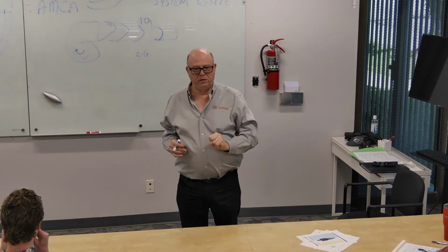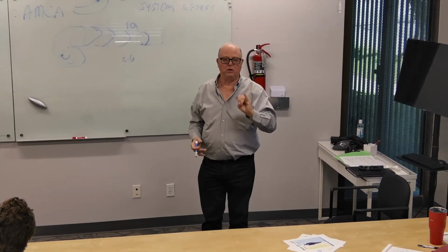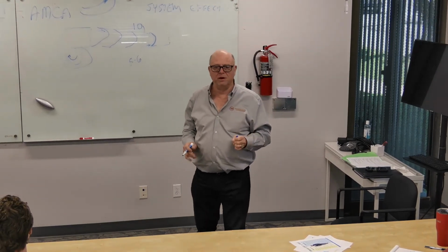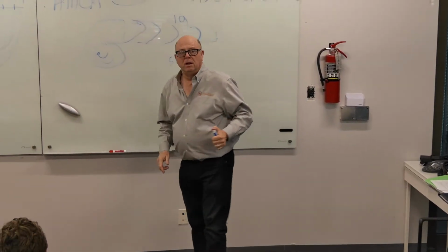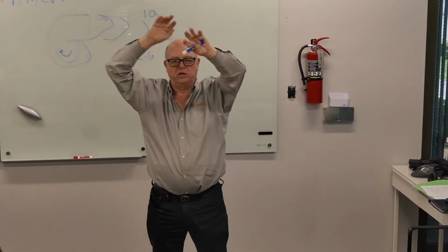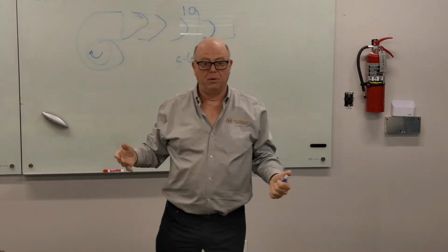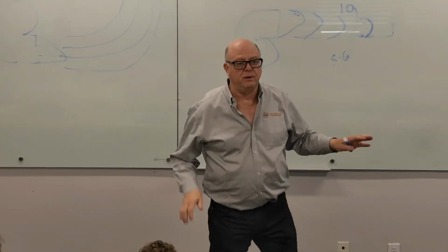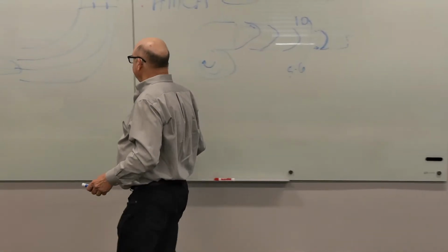I mentioned energy, right? That's one thing. I mentioned loss of pressure. There's one other different kind of, but just as important impact to turbulence. Anybody have an idea? Sound. Sound, yeah, that's exactly right. Duct rumble, which is what you call it in large ducts. And the broader the surface area of the duct, the more potential for rumble, bass drum type effect you get. That is all caused 100% by turbulence. We want to minimize that.